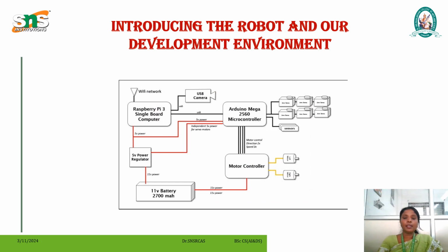Here we see the development environment of our robot. The entire robot runs on one battery. You may want to split that and have a separate battery for the computer and the motors. This is common practice, and many of my robots have had separate power for each. Make sure you connect the ground wires of the two systems together.